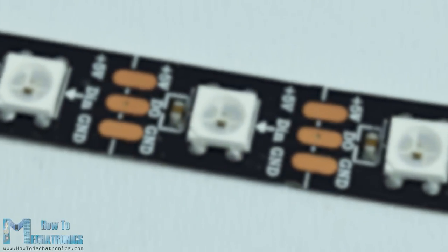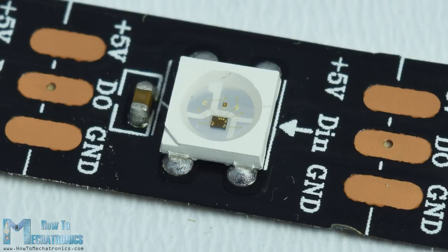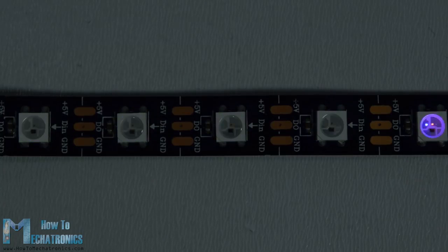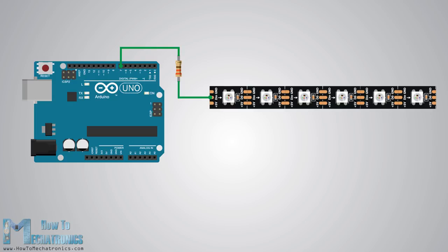Let's start by taking a closer look at the LED strip. It consists of type 5050 RGB LEDs, in which the very compact WS2812B LED driver IC is integrated. Depending on the intensity of the three individual red, green and blue LEDs, we can simulate any color we want. What's great about these LEDs is that we can control even the entire LED strip with just a single pin